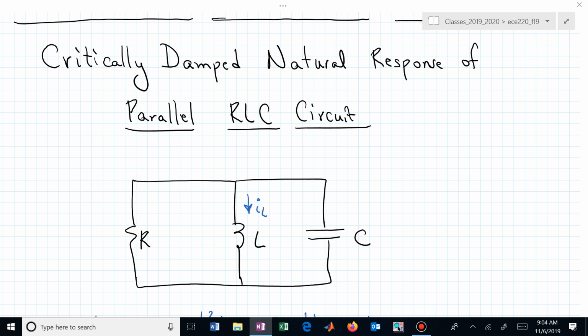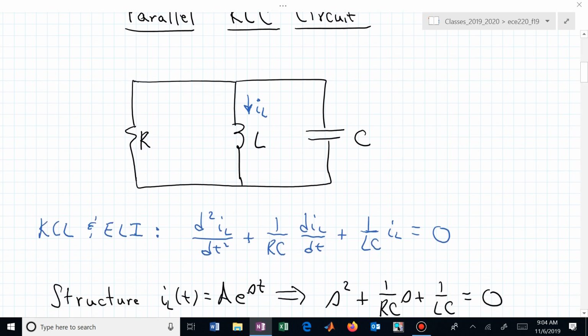If we now introduce some resistance, depending on how much we introduce, it throws us into one of the 3 different patterns. It's maybe difficult to comprehend going from infinity to gradual, but we're coming in from a larger value of R to introduce damping into the circuit. We go from purely oscillatory to damped oscillatory. Then as we make R smaller, we get into the critically damped and then the overdamped. We're talking today about the critically damped, where we have 2 real equal roots of that characteristic equation.